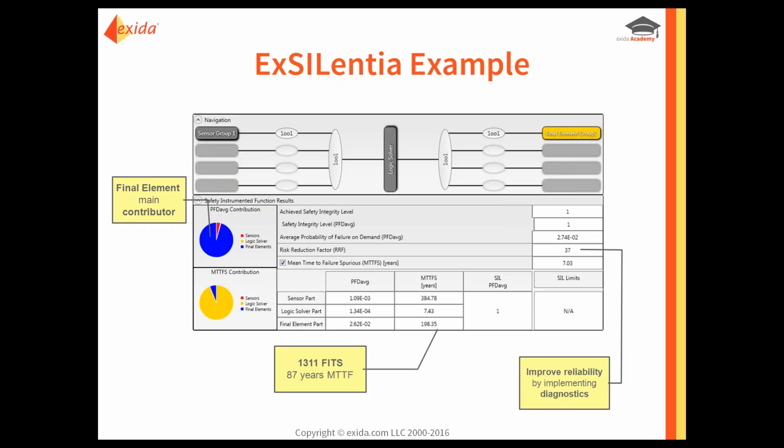Say you need a larger risk reduction. Great, we can change that. Say you need a different PFD average or a different SIL level. There's ways that you can pick and choose. You can change your architecture. You can change the product type or the product, the people that make the product, and see how you do better or worse in different situations. So if spurious trips or safe failures are something that you're concerned about on your plant, there are ways to help you reduce those.